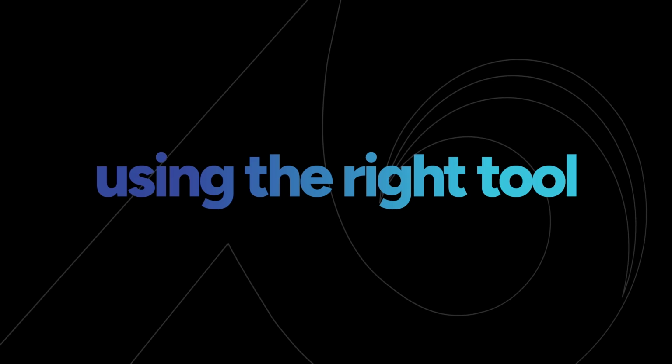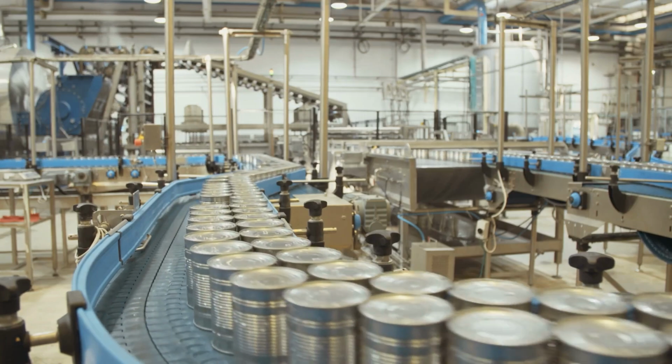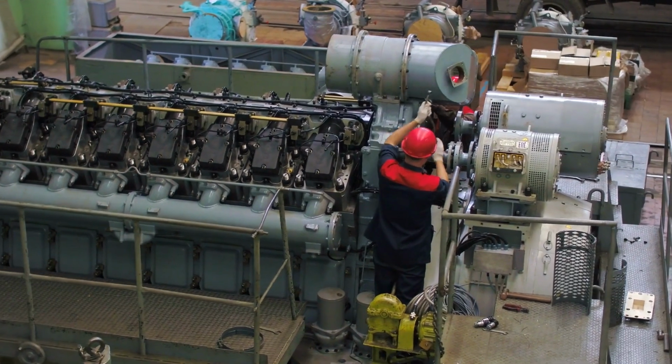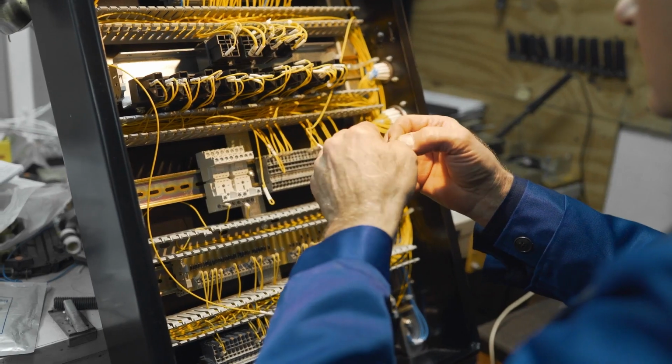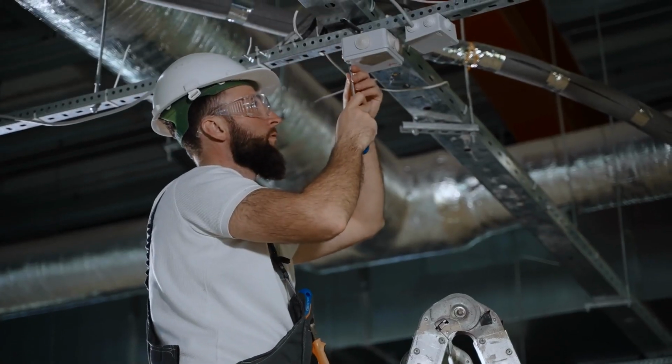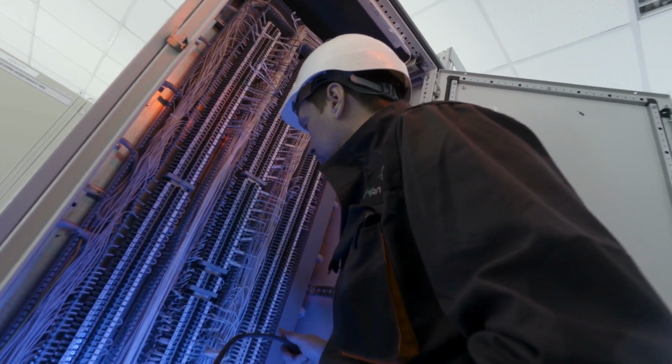Now, one way to counteract dangers in all areas is through engineering controls, or in other words, using the right tool for the job and location. Since all electrical devices use a current of some kind, only approved equipment must be used in hazmat areas. All equipment, wiring, and installations should be identified as intrinsically safe and approved for the specific classified location.